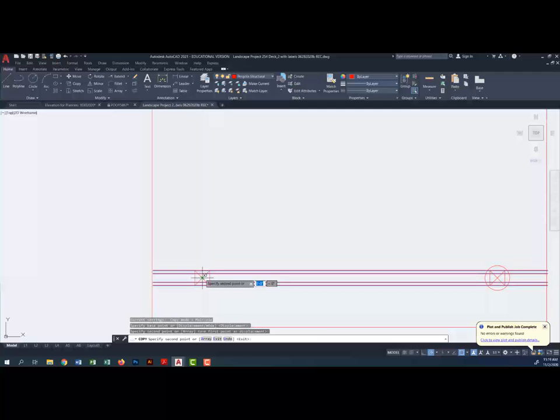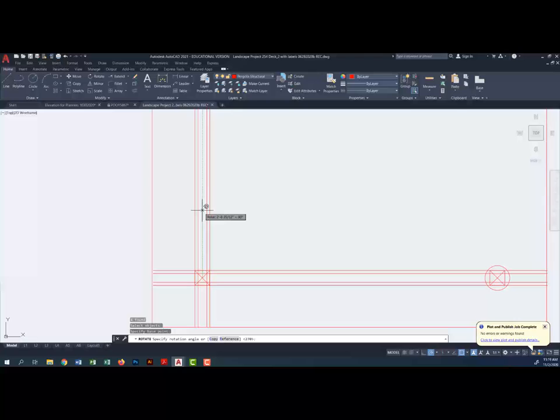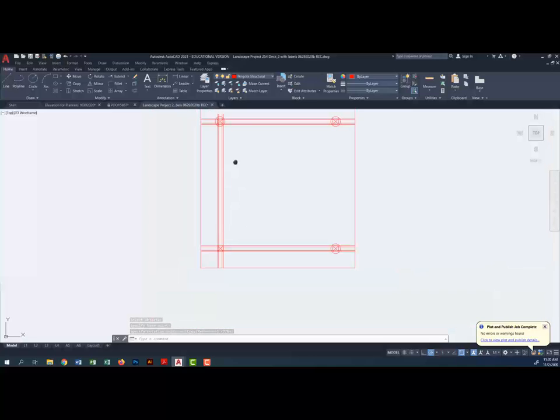Now, what did I do? I've got 2 layers of these lines on top of each other. Now I'm going to rotate, and in order to pick what I just did, I type in P and enter for previous. And it's only going to take the top lines as opposed to the bottom, and my selection, click on the center, and move in the vertical direction. And see what it did? It didn't take all the lines, it only took the previously selected lines.